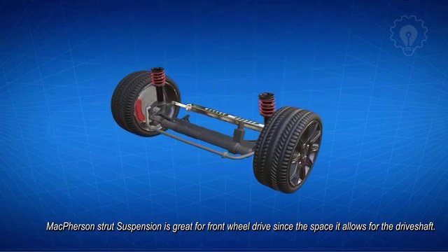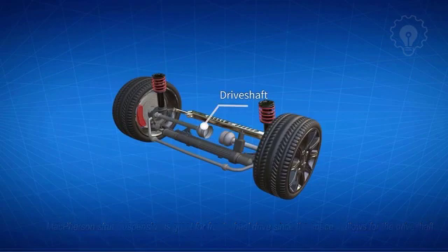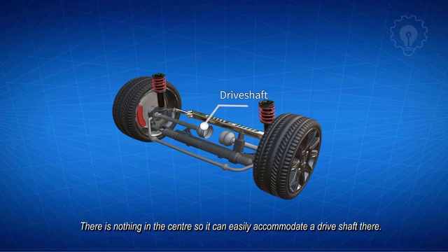McPherson strut suspension is great for front-wheel drive, since it allows space for the drive shaft. There is nothing in the center, so it can easily accommodate a drive shaft there.